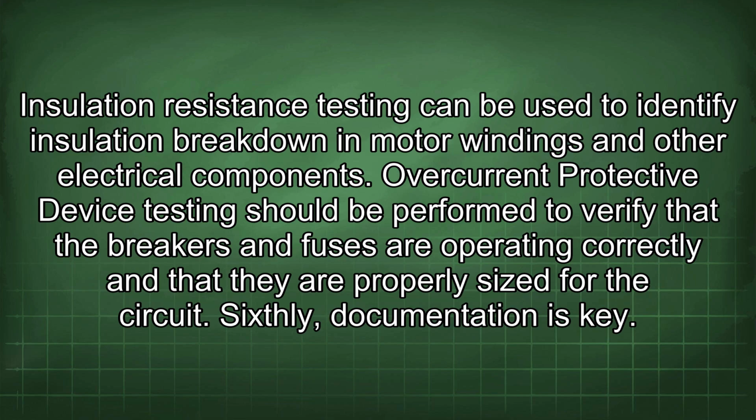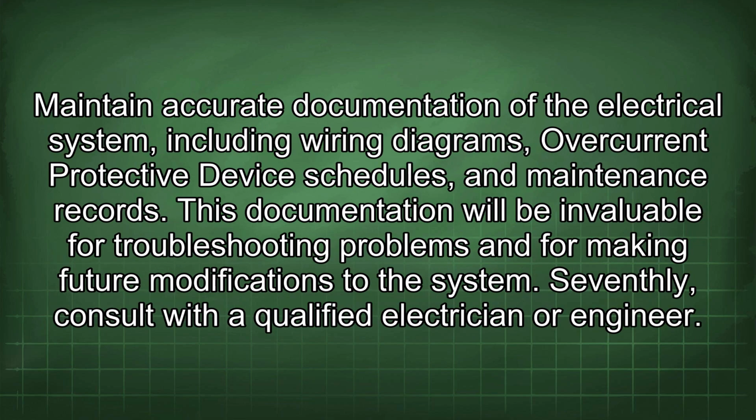Sixthly, documentation is key. Maintain accurate documentation of the electrical system, including wiring diagrams, overcurrent protective device schedules, and maintenance records. This documentation will be invaluable for troubleshooting problems and for making future modifications to the system.